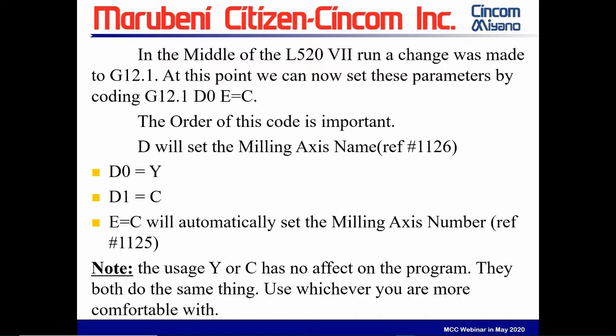And the Y and the C are nothing more than a character. They're exactly the same. It's very important to realize that. By programming with C, you are not programming the C axis. You are programming still the Y axis move inside there, which is not happening with the virtual Y.